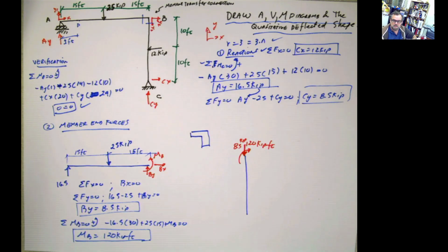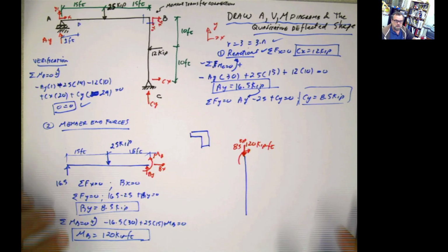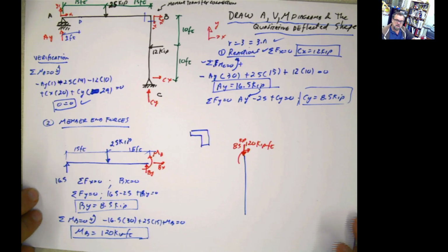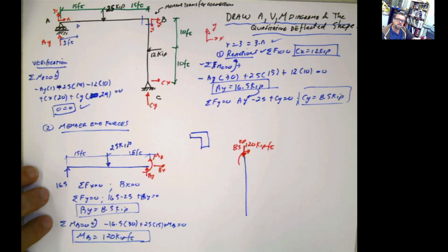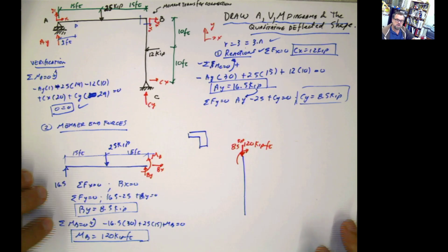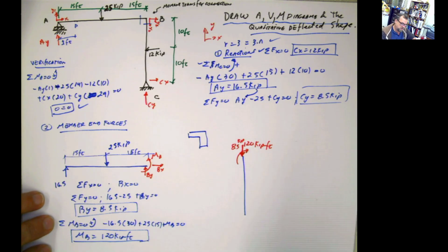You can have plates connecting them. If it's reinforced concrete, you're going to have the rebars coming and entering into the other member with the development length or splicing and everything else that you need over there. And by the way, there is a whole design that you have to complete for that joint. You don't learn it here in this class, but you have to design the joint also. One of the most important parts of the structure are the connections, the joints.